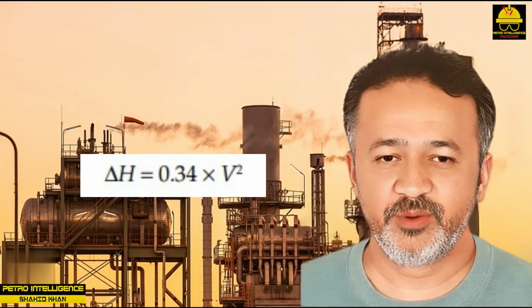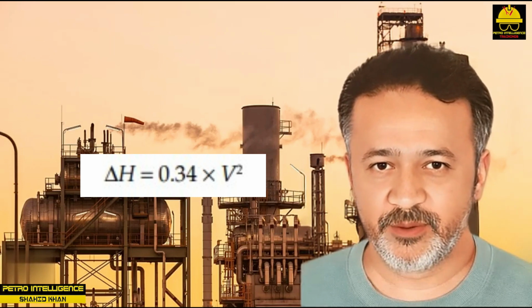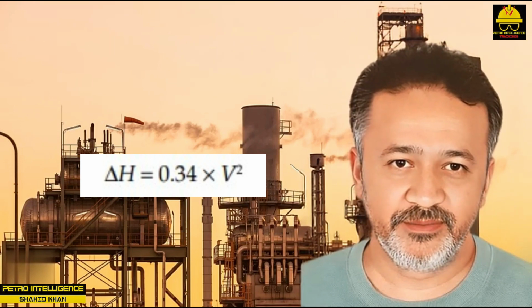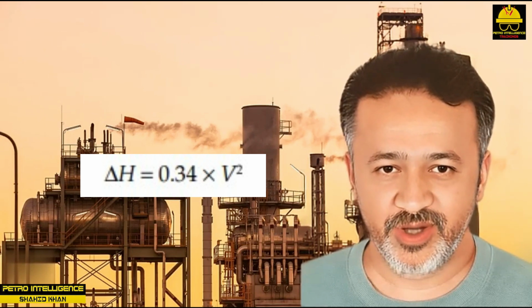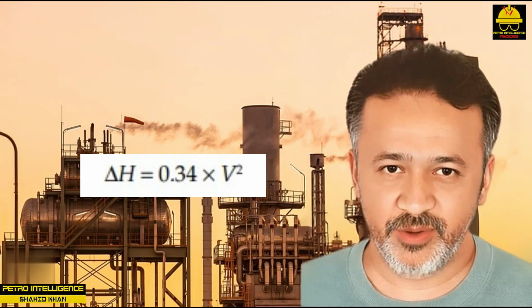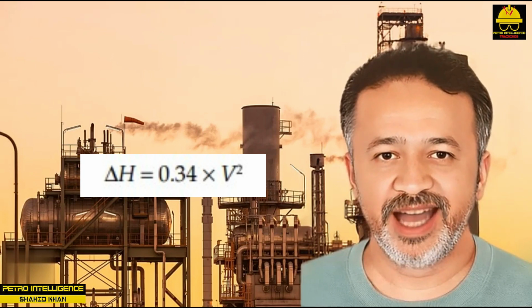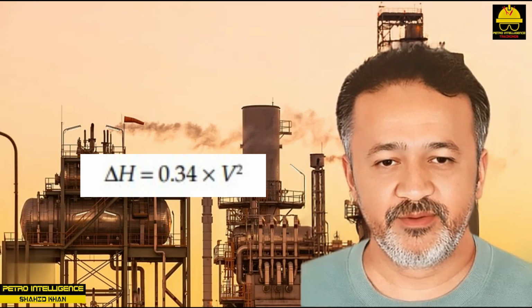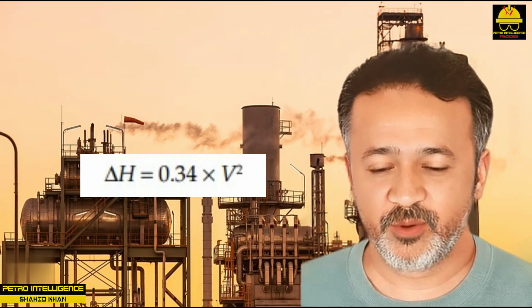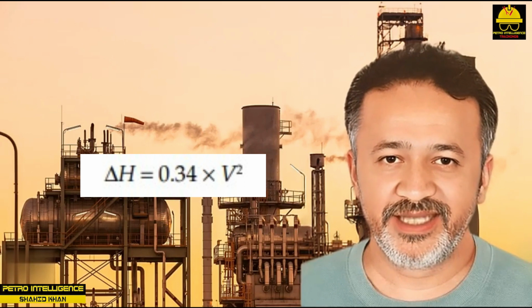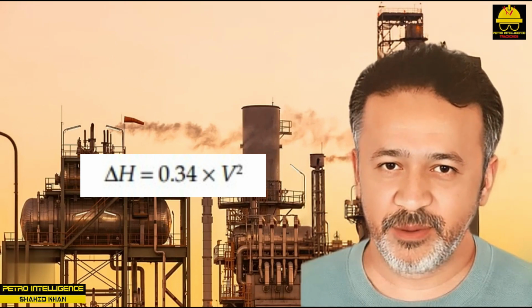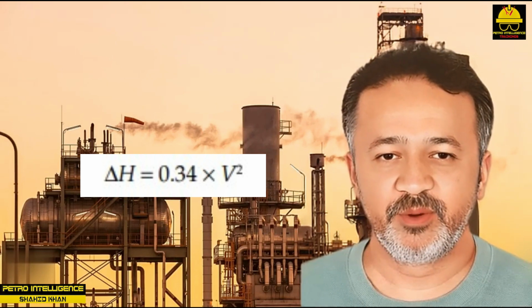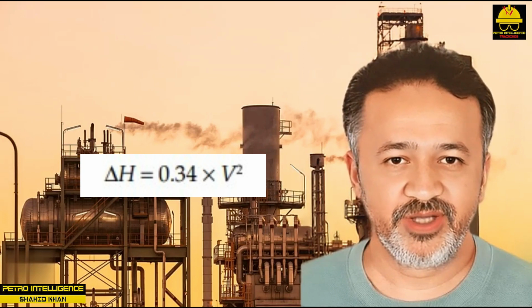The energy to accelerate the fluid in the draw-off nozzle comes from the potential energy of the fluid. This is Newton's second law of motion. The coefficient used in the equation above, 0.34, assumes the process fluid has a low viscosity. For most process nozzles, this is a reasonable assumption. Detailed information on draw-off nozzle coefficients has been published in Crane, Flow of Fluids Through Valves, Fittings, and Pipe, Technical Paper 410. For me, I don't trust published coefficients.